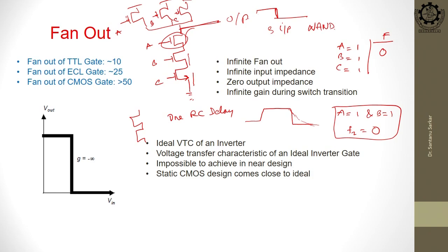Getting my point? When this MOS in a digital gate is on, it will be on in which mode? Linear mode, right, because in linear mode its resistance is less. In digital I only have cut off and linear. So linear means I can replace this with a small resistance value R1, and this node will have some capacitance. Next, this MOS I can also replace with a resistance and another cap at that node.